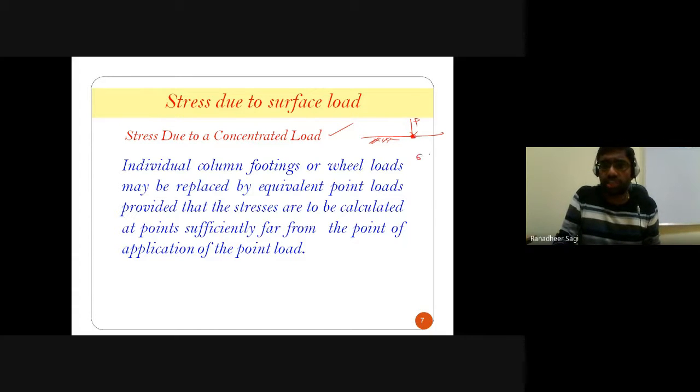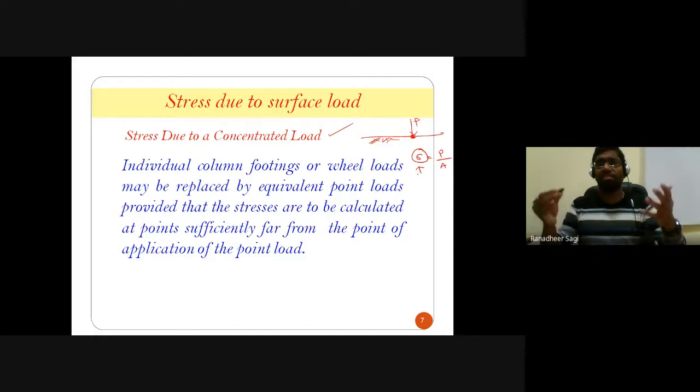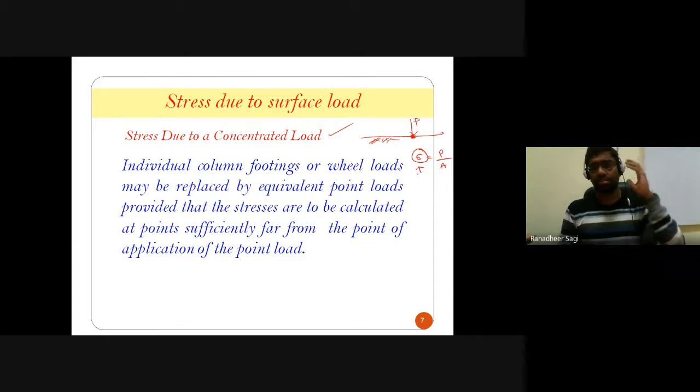Generally, whenever we talk about stress, in simple terms it is force acting over the cross-sectional area. Now, what is the area of contact over which that point force is acting? The area of contact is a point contact. The area is relatively very, very small. So if the area is very small, then automatically the stress we calculate for that point, immediately where your point load is acting, is relatively very, very high, and in general terms people say it is infinity. Infinity doesn't mean something you cannot define, but it's a relatively very high value.